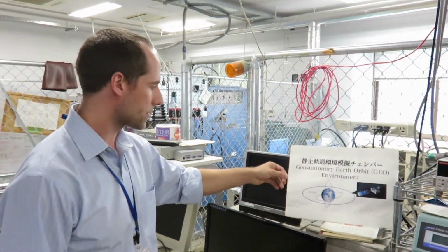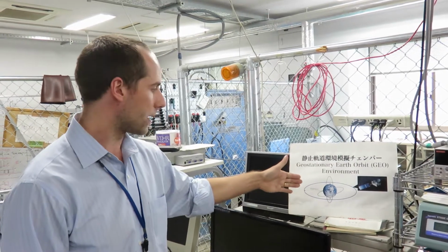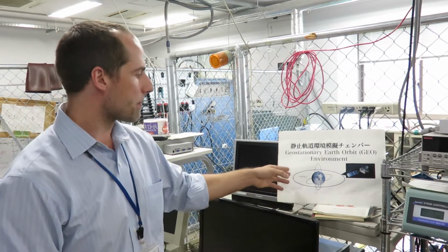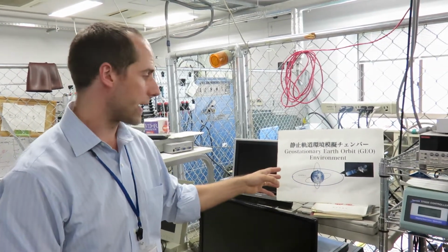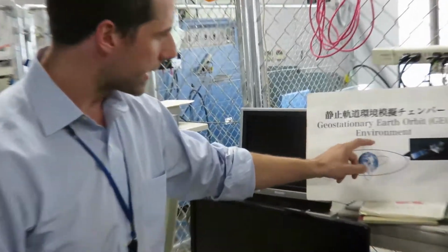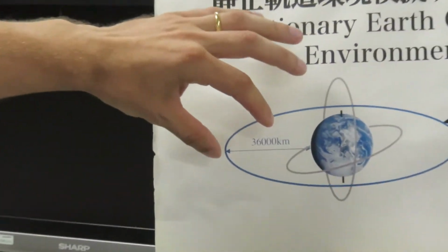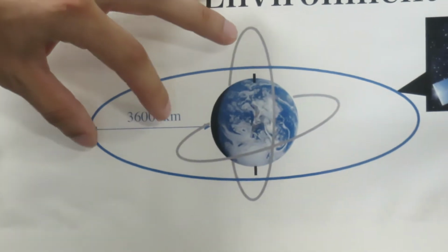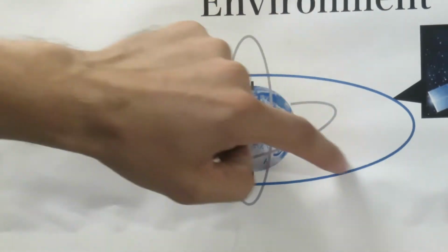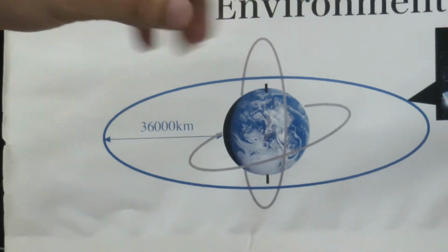So in some ways advantageous to geosynchronous. But this is an ideal location for communication satellites, for television satellites, and many other large satellites. And this is a much more extreme plasma and radiation environment. Before I talked about the Van Allen radiation belts, the inner belt is just outside of LEO, which I described before. But the outer belt is actually primarily just inside GEO. So in this region and this region, there's a fairly large, intense radiation belt.